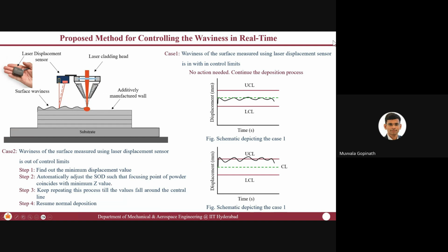Yeah. So now, one is, when should the sensor respond, or when should your power be adjusted, or when should your SOD be adjusted. Someone should tell the machine that you are now supposed to change your course or the standoff distance. Again, how do you make it smart? All that happens by a displacement sensor.